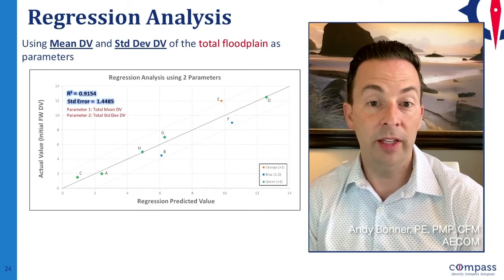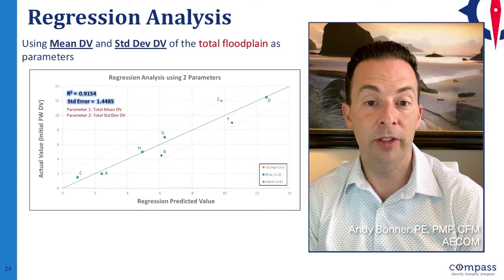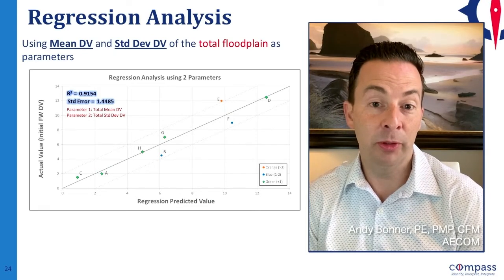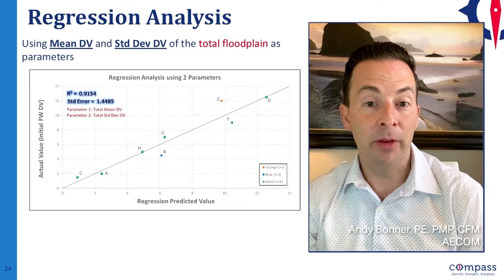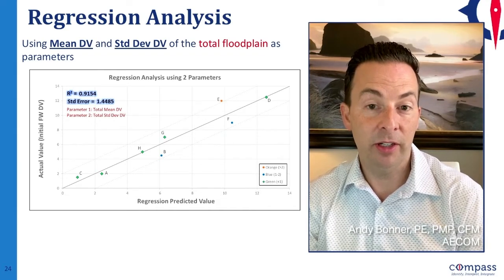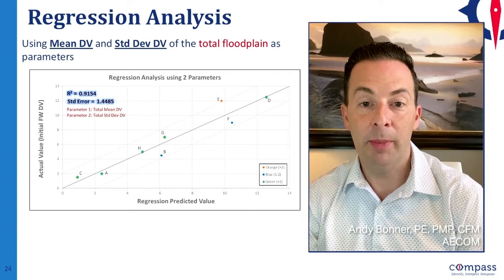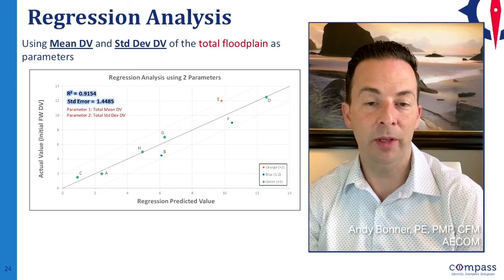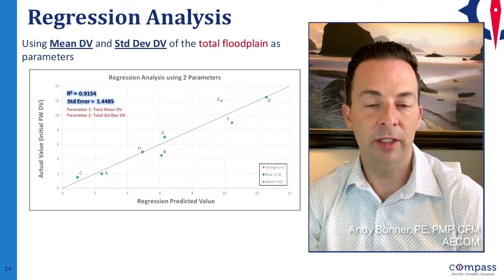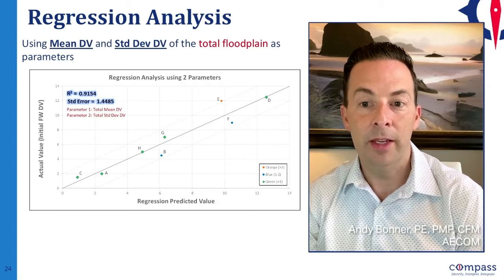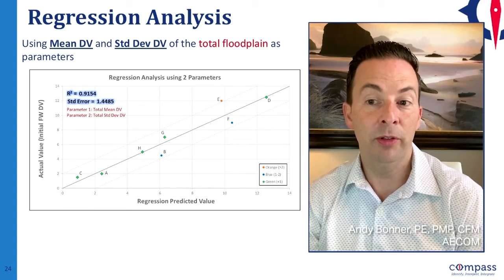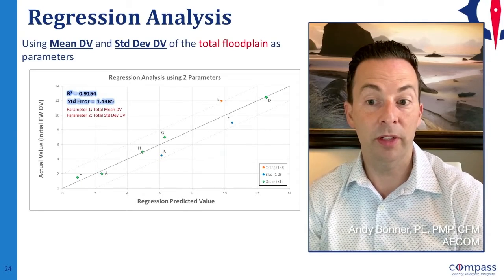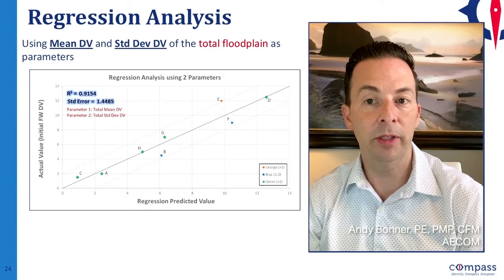requirements. So one of the takeaways from this is that even if it's premature to publish an actual equation as guidance until more streams can be analyzed, at a minimum, there's optimism that we could provide a suggested starting depth times velocity value for a mapping partner to produce an initial floodway encroachment that would at least put us in the ballpark of something that would produce a surcharge-based floodway in compliance. And hopefully this could be at least a way to reduce the number of 2D floodway iterations that might be needed to land on a final delineation that both meets that equitable consideration standard and surcharge requirements in place.